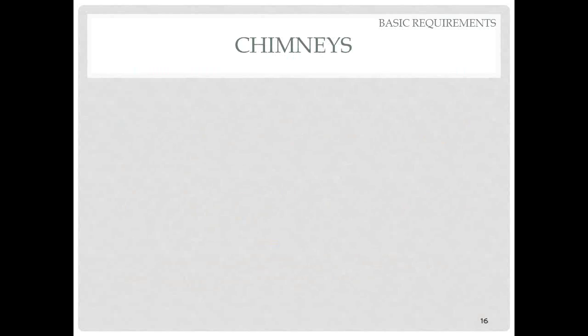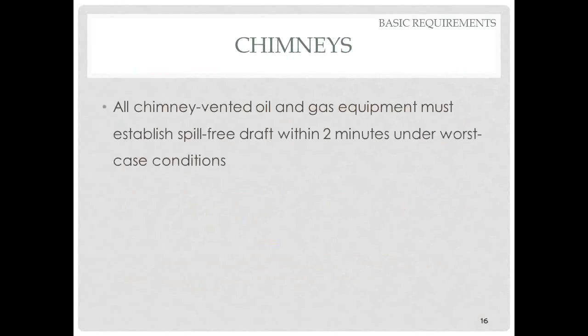There's also a requirement for chimney venting. All chimney vented oil and gas equipment must establish spill-free draft within 2 minutes under worst case conditions. Worst case is when the building is completely buttoned up, as airtight as it can be, and basically all the exhaust equipment in the building is operating.